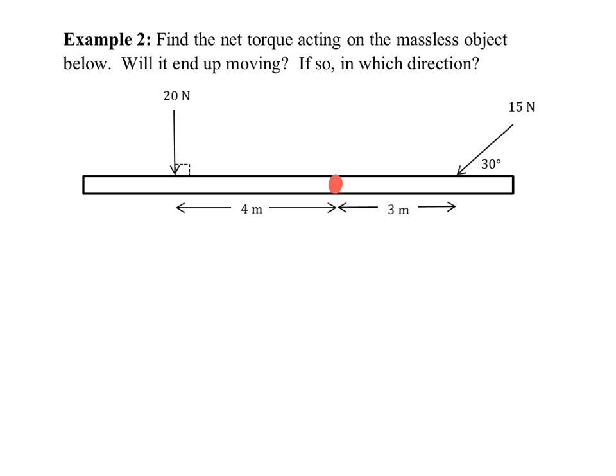And here's a nice way to see it also, ready? There's the fulcrum. Follow the arrow and kind of like just draw it out like that. See what I just did there? Like it's almost like you're following the direction the arrow is pointing in. So had that arrow been the opposite, let's take a look, please, ready? Had this been a force applied like that, well then follow that arrow and try to loop around the fulcrum. It would have caused the opposite type of rotation. It would have caused counterclockwise.